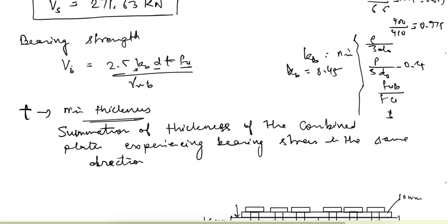Because it is a lap joint in this current case, if there is this bolt, and we are pulling it here and this one pulling it here, then in this upper part the stresses will be developed on this face, whereas in this part stresses are developed on this face.